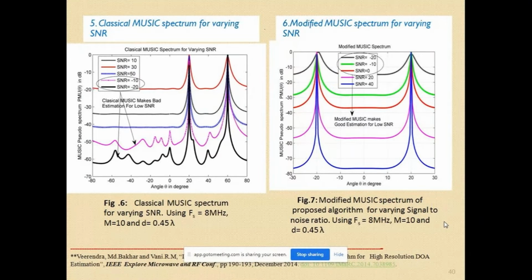antenna algorithms. Smart antenna algorithms like the MUSIC algorithm, and algorithms like Estimation of Signal Parameters via Rotational Invariance Techniques, and their improved or modified versions. Here we would like to stress this more, because this is the practical situation where we could face many challenges in signal to noise ratio conditions. And with the signal to noise ratio at 50, 30, 10, etc., we could see that the directions of arrival are estimated accurately. The directions of arrival considered here are 20 and 60.